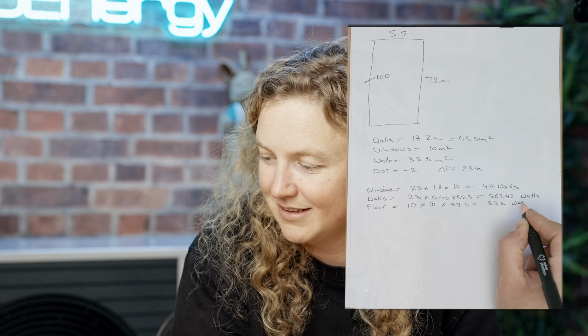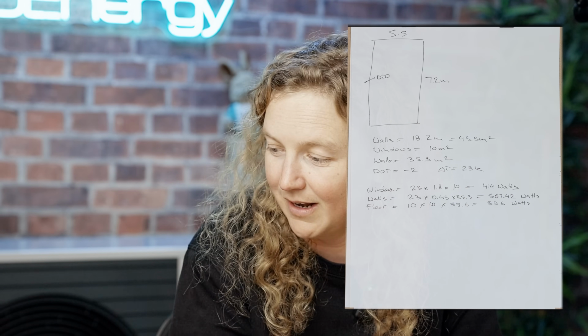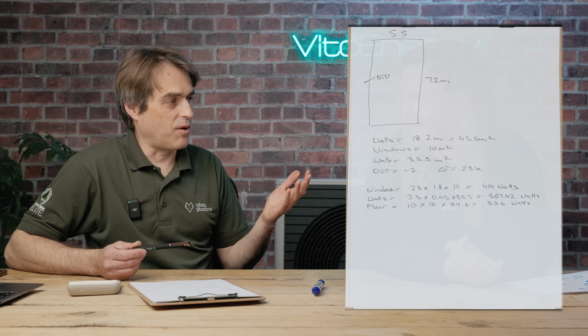So yeah, it is 396 watts. You've assumed that your U value of the floor is 1. Well, I don't have it. If it's 1, yeah, exactly. Which actually by coincidence, it's an uninsulated floor. Yeah, that might be reasonable. Is the U value between 0.7 and 1.5? Depends a bit on the geometry of the floor, so how much exposed perimeter and area it's got, but typically around 1.